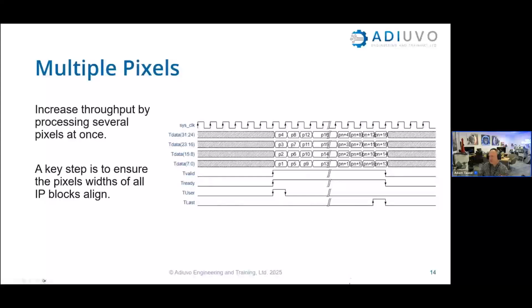So this pixels per clock is really important, because it allows us to get that throughput. A few years ago, we did some image processing, and I should have put this slide in actually, where we needed to be able to do thousands of frames per second, actually tens of thousands of frames per second. And it was really impressive just to see how big a difference it made by changing the number of pixels per clock on that throughput as we were running through.